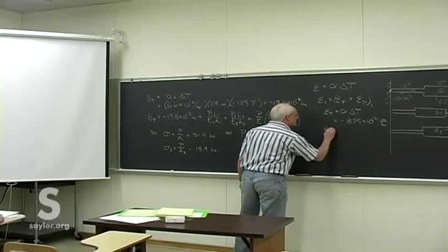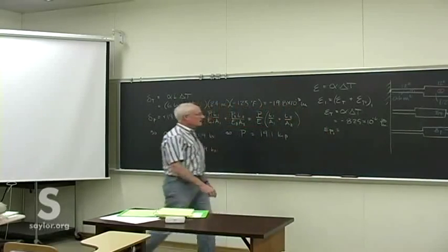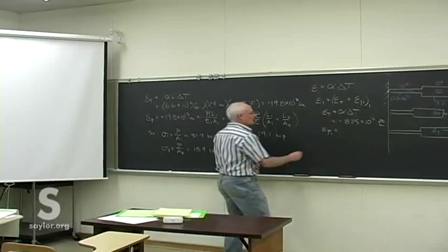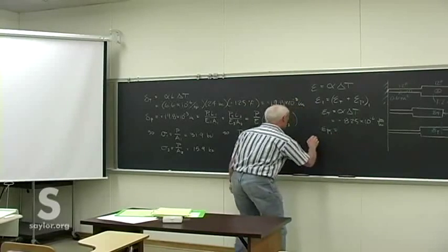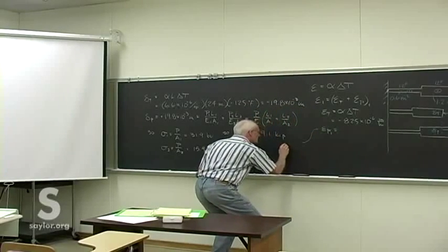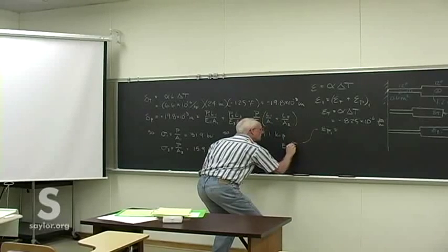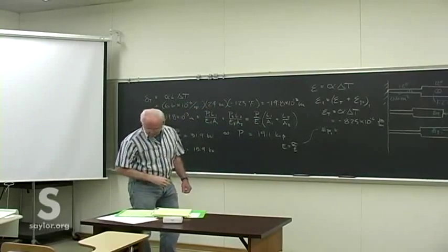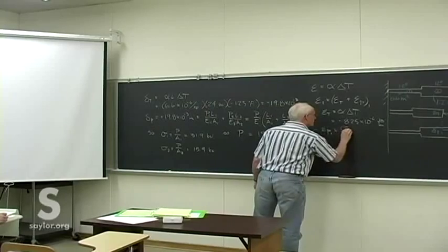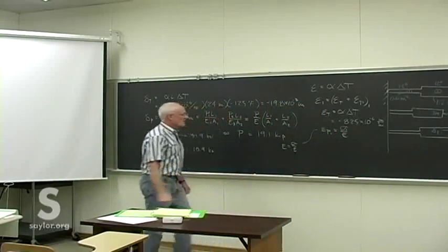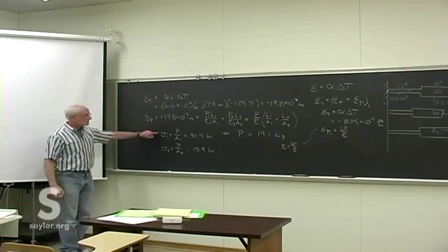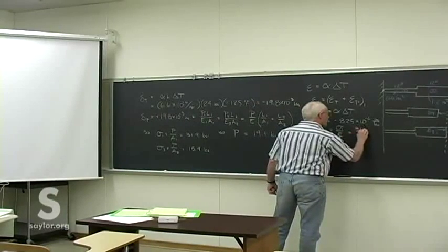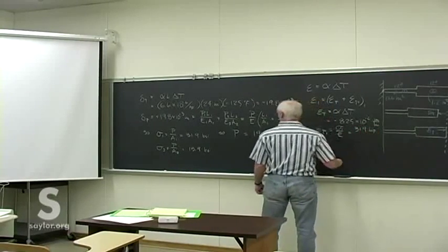But we can get the mechanical strain for piece 1, remembering that Young's modulus is defined as the stress over the strain. It's been a while since we looked at this. So we know that that's going to be the stress that we just found over Young's modulus for the material. So the stress we just found is the 31.9 KSI.